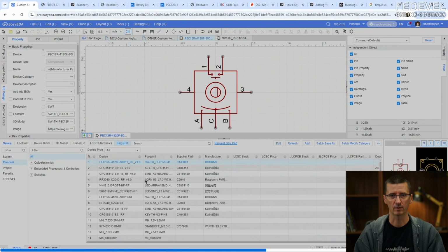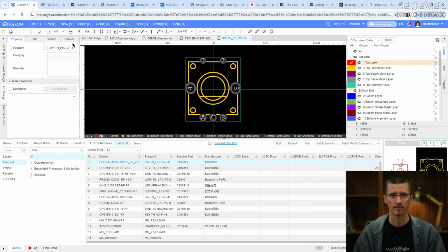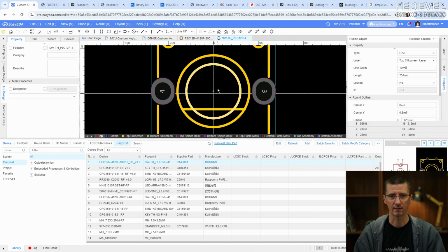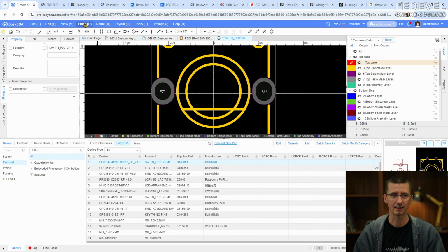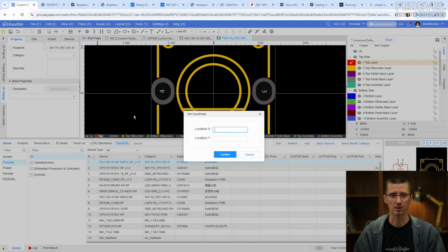And we would like to edit also footprint, or double check the footprint, just to be sure it is correct, because this is moved a little bit. I think, notice, see, it's moved. It's not in 0, 0 position. I don't know why they created the footprint this way, but we are going to move this origin.